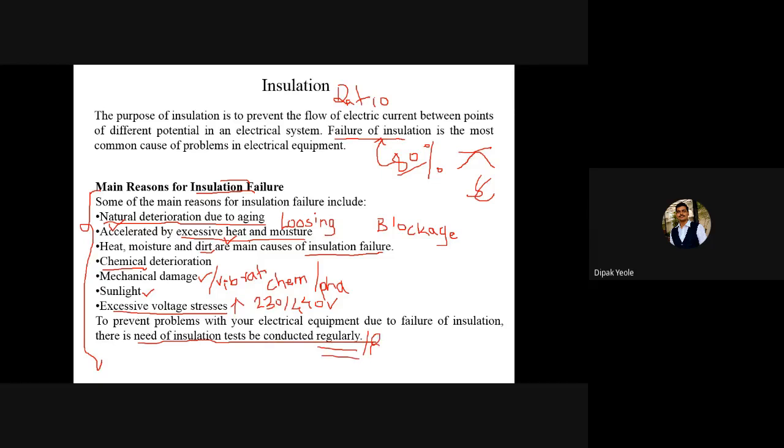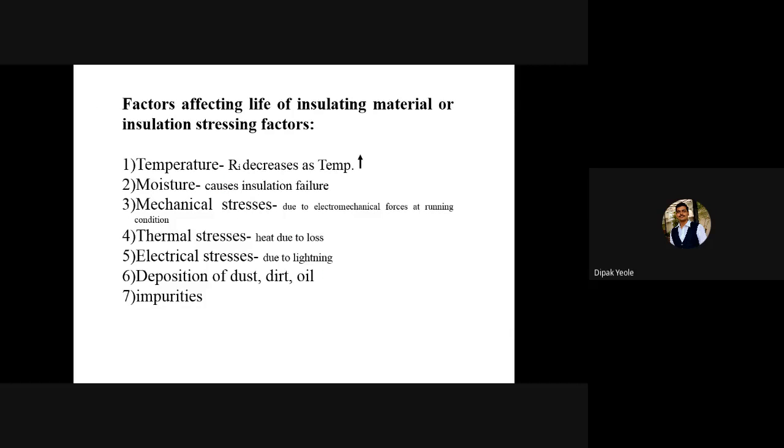Routinely we have to carry out the insulation test. Believe me, if you carry out the routine test for the insulation, then you can minimize these reasons of insulation failure by 80%. Yes, so these are the main reasons of insulation failure. Now we will go ahead.